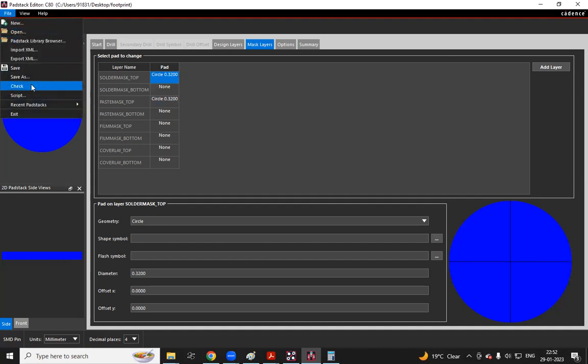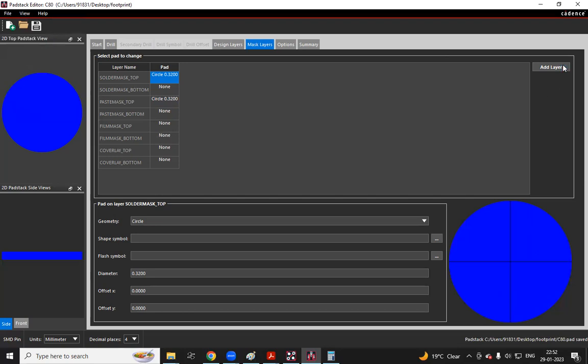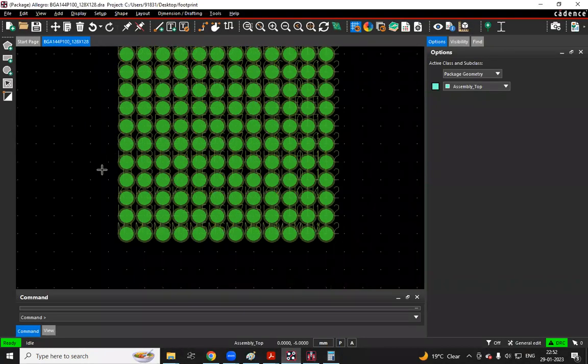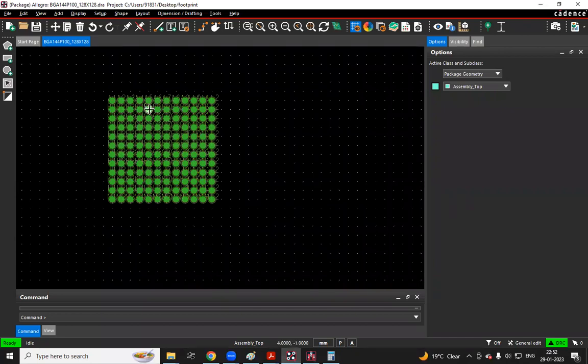Okay, file saved. So guys, here you made a mistake placing these pad stacks. So again I have to delete all, right? Replace. We can replace, no? Guys, we have to delete. No, what options can we apply there? Replace. Correct. Yes, replace. So in one step we can replace all.